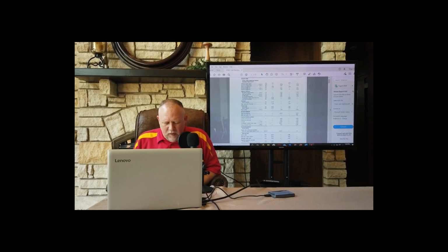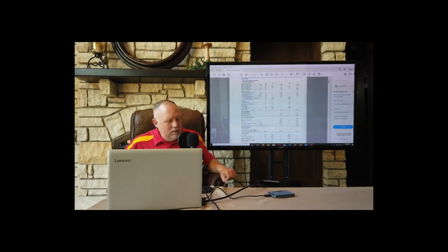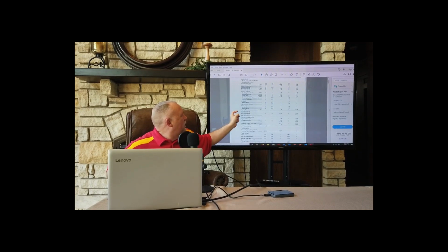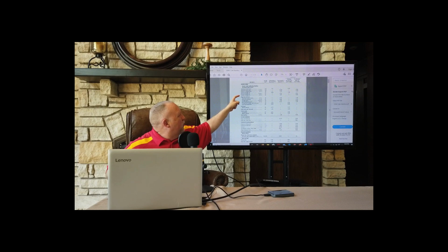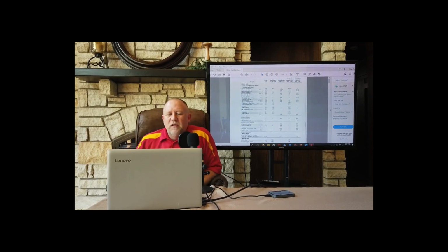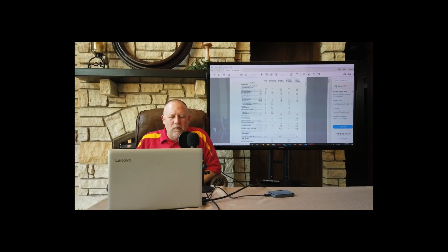All right. Going down, let's see. Oh, on an exterior of a wood wall, you might have probably plywood, like a Douglas fir plywood. That's fine to use. It gives it to you in thickness per inch. That's at 1.25. But it also listed 1/4 inch plywood, 1/2 inch plywood. So if I gave you something that wasn't that exact dimension, you could use the thickness per inch and multiply it out.